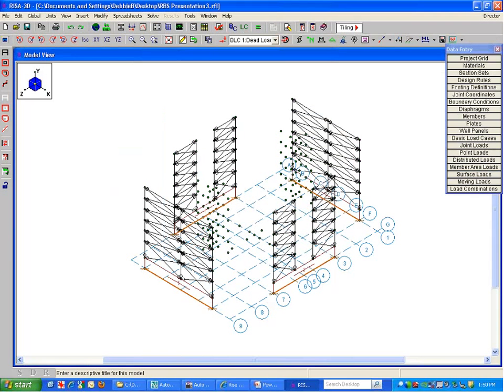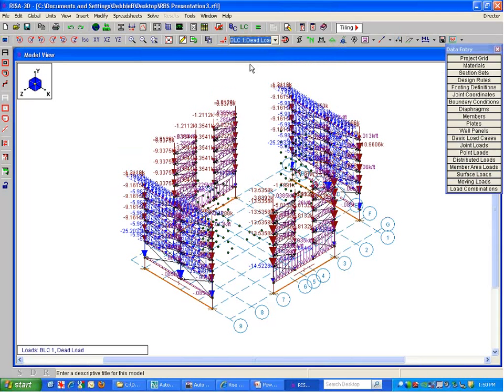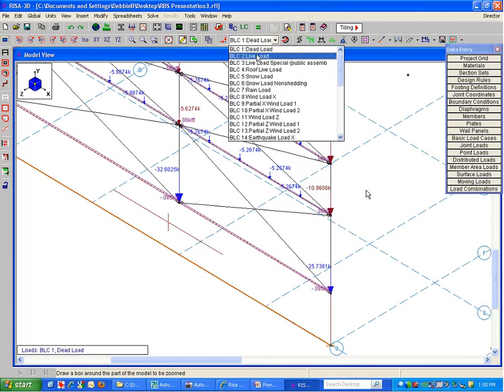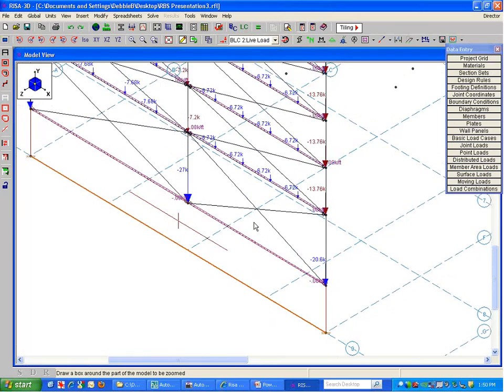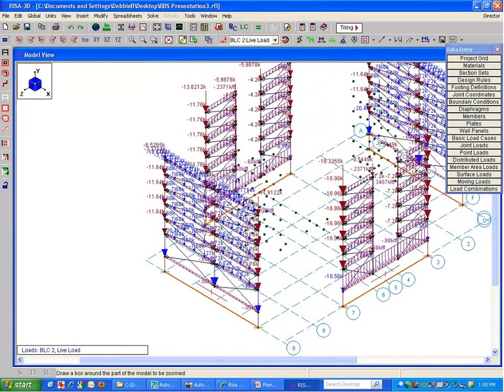The only thing that got transferred into this model is the lateral members. So only that was red there in the previous model is going to be carried in. And now that first it might make you nervous that you don't have enough of your loading in there, but you can see you have the dead loads and the live loads in here. And I'm going to zoom in a second here, and I can see that every place that an actual beam or joist framed into these members, I actually have the dead load, I have the live load. So it's all accounted for. All of that loading is actually accounted for, and there's no worry that you lost load.